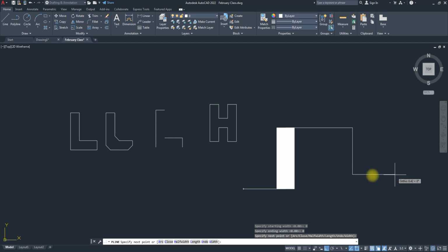And we have that. So what if I want to create an arc? I can also create an arc with this polyline. Mind you, I've not stopped this command, I'm still working. I can say, okay, I want to create an arc. I'll just choose A for arc, press enter. You can see what I'm having. The reason I'm having this semicircle arc is because of my auto mode. It's constraining it to horizontal, so I'm having 180 degrees, a semicircle.